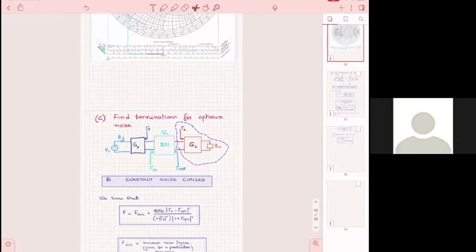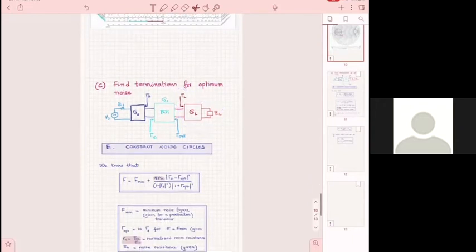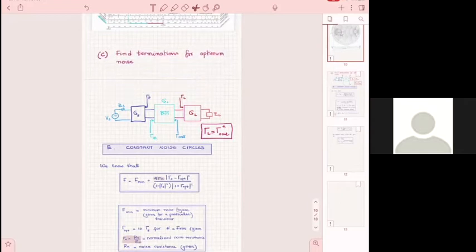And the maximum gain of the output matching network comes from gamma L equals gamma out complex conjugate. So I'm going to have this for unilateral, all right? Let me move this higher and write here unilateral, so you know it's the unilateral case.